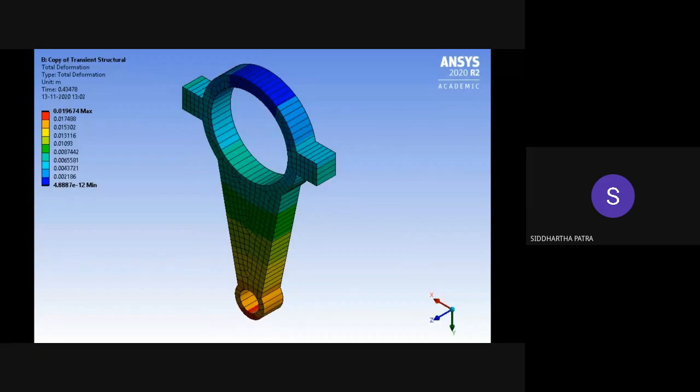In that larger circular hole, I find the highest point inside the hole and make that the pivot point. I would place this connecting rod at the highest point of this largest circular hole on a knife edge.